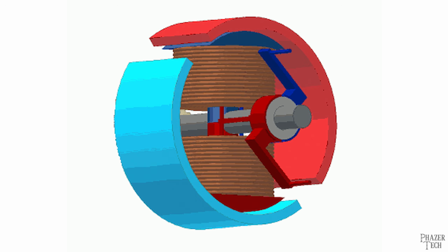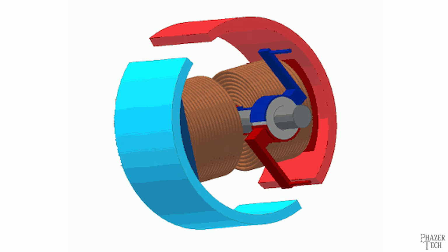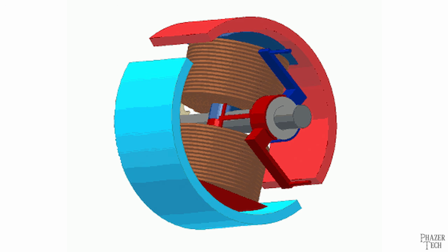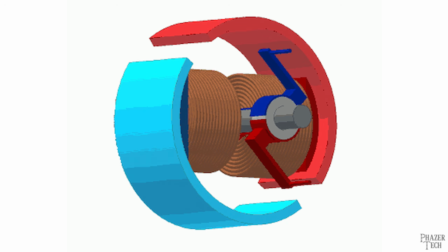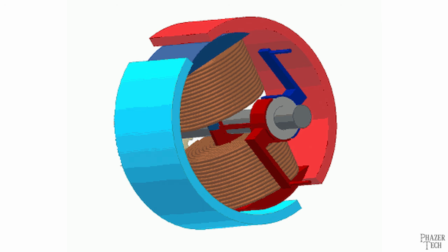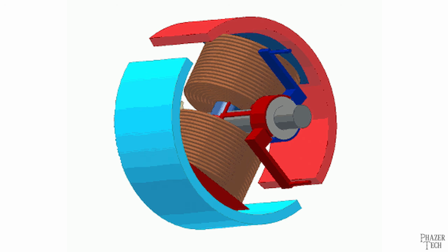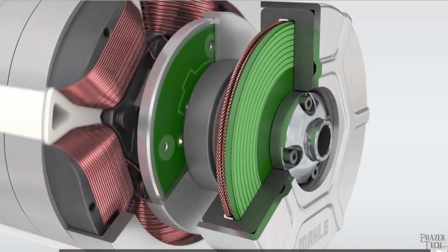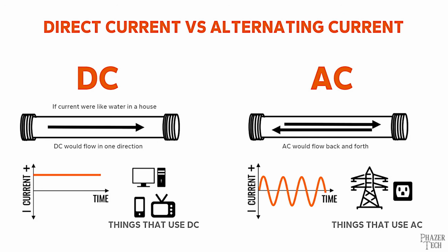These components are orientated in such a way that it will continuously spin the motor's shaft as long as the coils remain energized. But it turns out there's many different ways to orientate these components, and each method offers different pros and cons. Also, larger motors typically don't contain permanent magnets, but rather they completely rely on electromagnets, since these can produce a stronger electromagnetic field. So let's now go over some of these different types of motors.